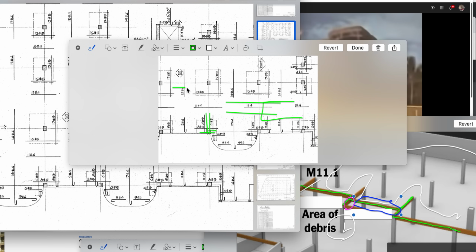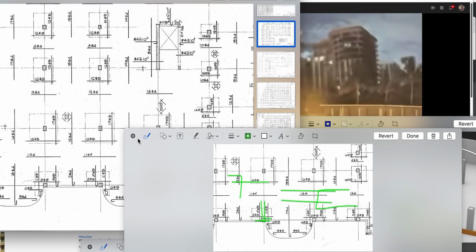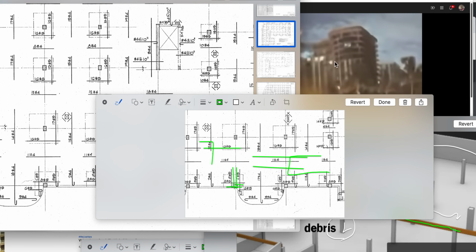That's why I talk about my ledger thing, my deck ledger repair. You bolt it in, and you make a bigger tributary at the critical shear area. You can literally, with money, put steel all the way across here and start tying this thing all the way across from here to there to there, and make a whole new steel internal framing to the darn thing if you want to. There's a rule that I have that says if you can't hide something, celebrate it. So you could make something pretty artistic in steel right on the outside if you wanted to. Exoskeleton, like this is exterior.